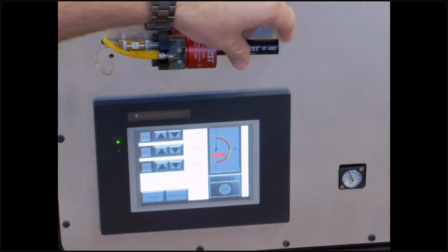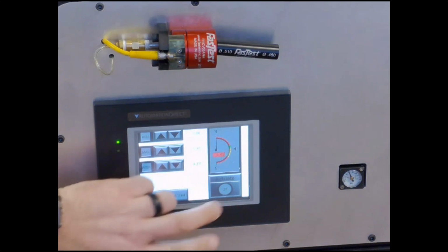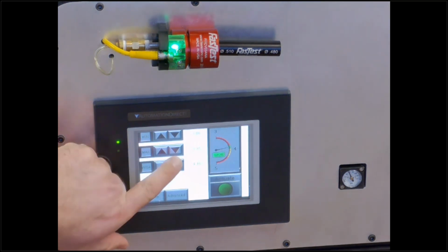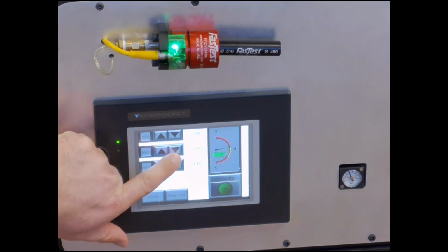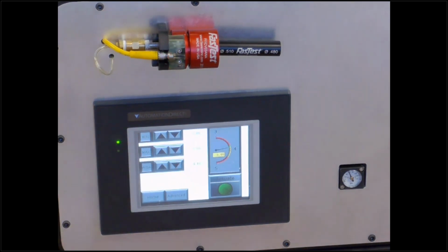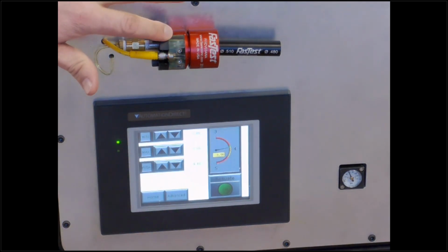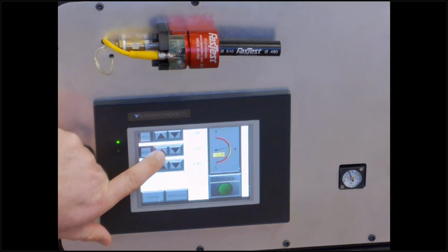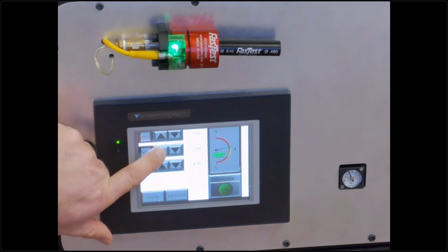I'm going to put the 510 end in there and actuate it, and we've actually had that set up to be in the good zone. That's a good leak-free connection. Now if I bring the maximum limit down, it's going to go out of range and the light is automatically going to go off. So I just did that with a few button presses. Really allowed you to set that range quickly to where we want it.